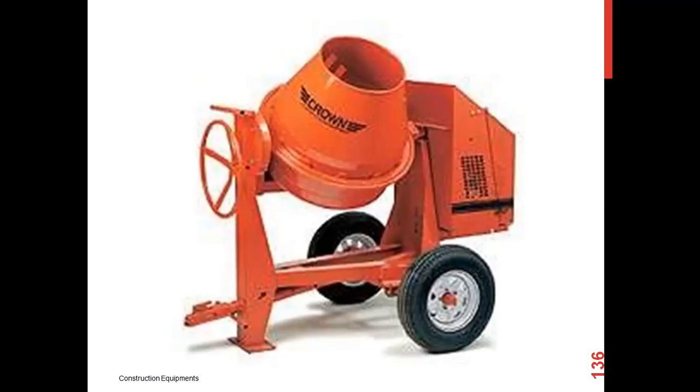Here, the amount of water which we discharge into the drum through the open end of the drum, the additional water arrangement, should be taken care of when making concrete. While unloading, this wheel can be rotated, so the drum with its entrance is turned downwards, and the concrete inside can be pulled out by a man who digs out the concrete which is in the drum.